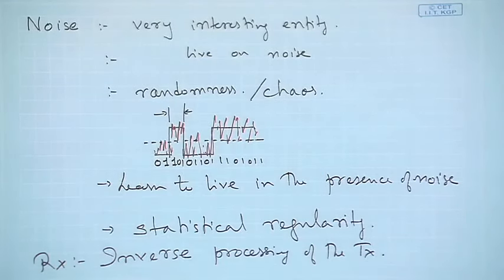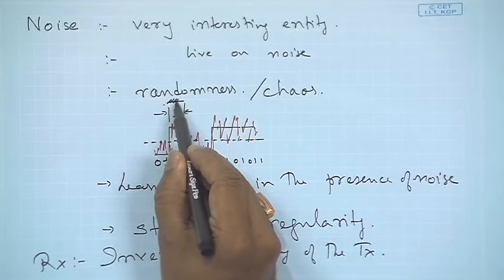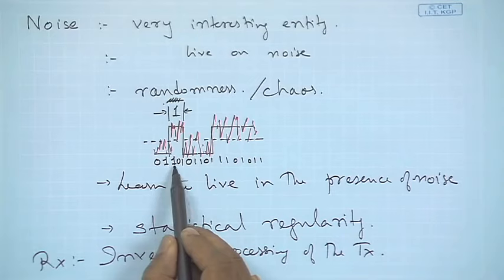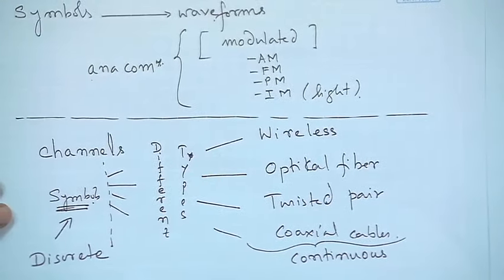So, we know that 1 was sent in this period of time, right. If 1 was sent in this period of time, in that case at the receiver, even if the receiver generates a 1 and a 0 in this period, we should actually take one of these two, or we should take a representative single bit for that duration of time. So, this indicates that time synchronization plays a major role in digital communications. So, the kind of time synchronization we have tried to depict over here is bit synchronization or clock synchronization. There is frame synchronization.